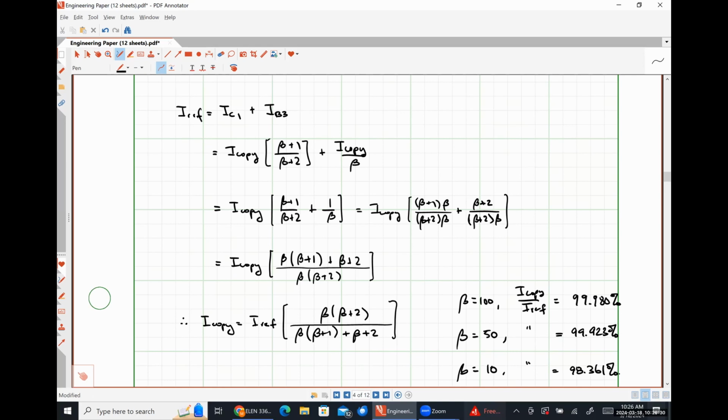In the best case scenario, we would be biasing these integrated circuit amplifiers with an ideal current source, where an ideal current source supplies some amount of current and its internal resistance is infinitely large. So the larger that we can make R out, the more like an ideal current source our transistor current source is going to behave, right? So having a very, very large output resistance is going to be very good.